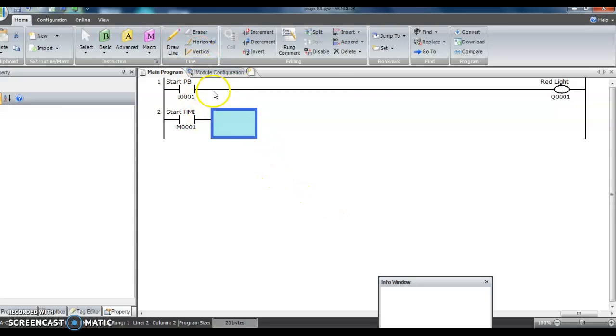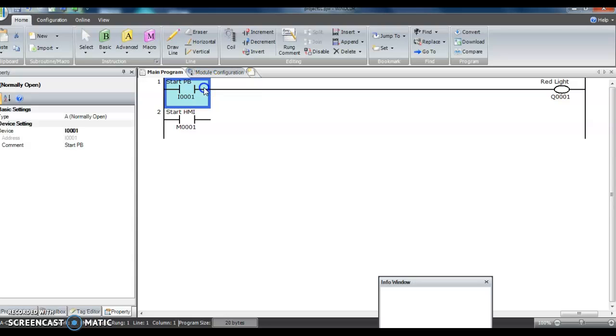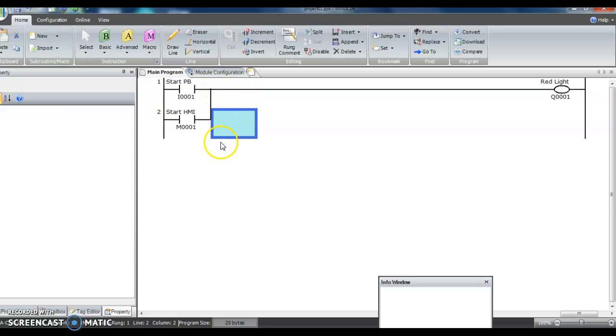And then we just need to connect it here. Remember making that little OR gate. Let's put it up here. And let's go shift down. Bam. That did it. Now remember, this is programmed, so we gotta re-download it.